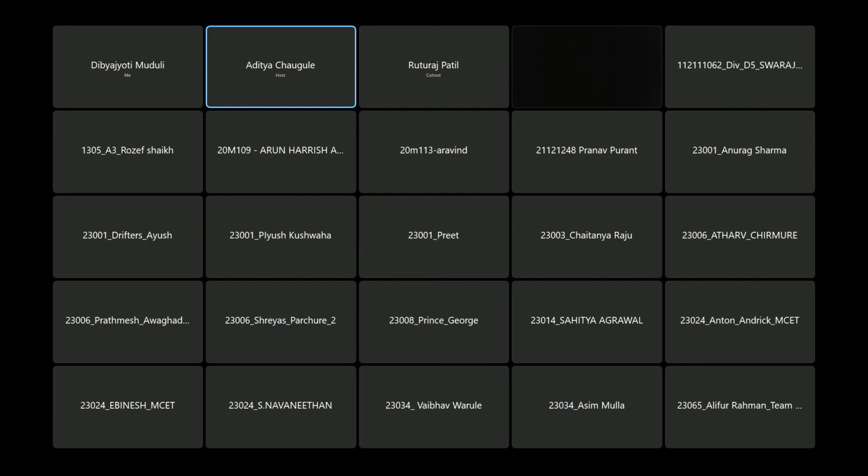For instance, powertrain is modeled in a different section, and suspension is in another. So ensure that you don't add any redundant masses, that is, adding the same mass twice. Just make sure that at the end of your vehicle parameterization, you have the entire vehicle mass similar to your real, physical vehicle, and similar to what you designed before getting started with the virtual vehicle model.